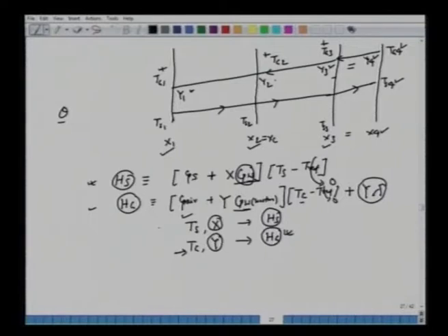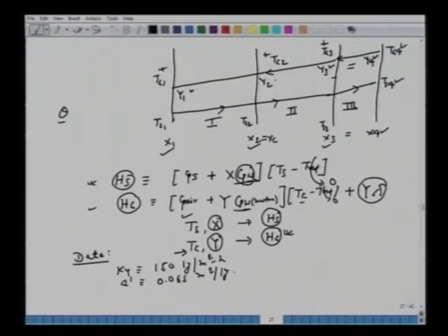All right. If you recall, in the earlier class we started with region 3, then region 1, and then went to region 2 to calculate all these thetas. Let's make note of certain other properties given to us. Some thermophysical data are given. Ky, the mass transfer coefficient, is 150 kg per meter square per hour. A prime, which we said is the specific effective area of drying, for the solid is 0.65 meter square per kg dry basis.